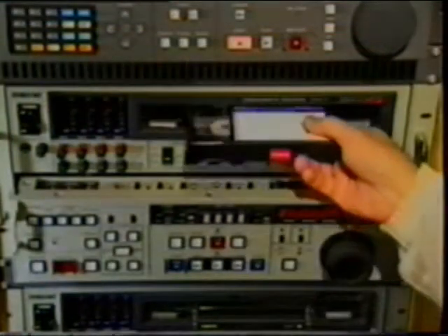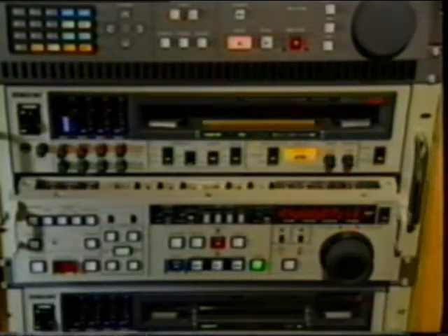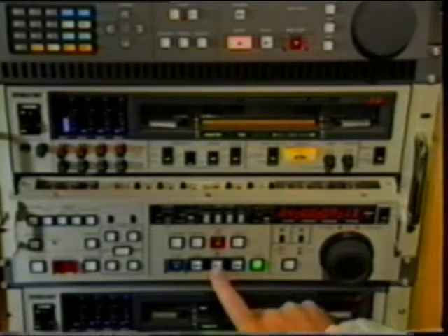If they fall short, it is too low. In either case, adjust the chrominance gain control on the VTR to place the dots in their boxes. That's how simple it is to make TBC adjustments. Just remember, TBC adjustments must be made while playing back a recorded color bar signal.